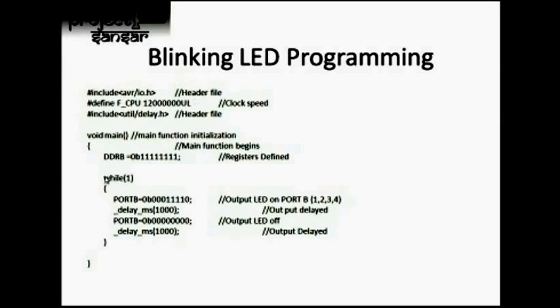Next what we do is define the while(1), which is the infinite loop. It simply means while 1 is equal to 1, you run the program. This would be a true case every time, and this program would run infinitely.